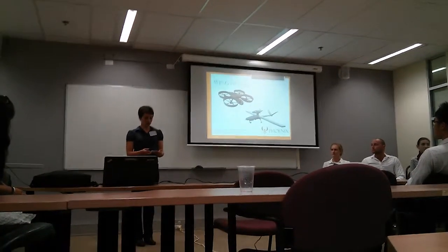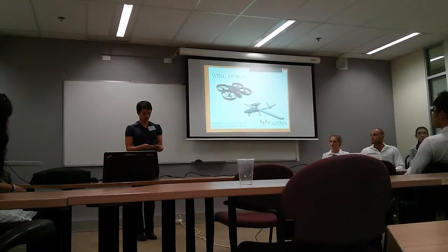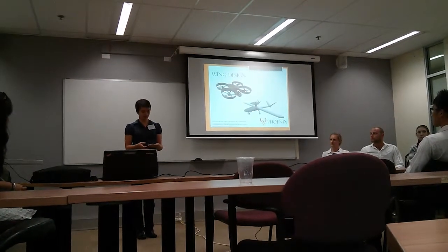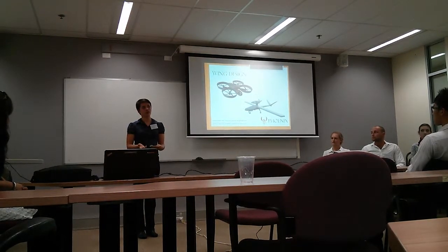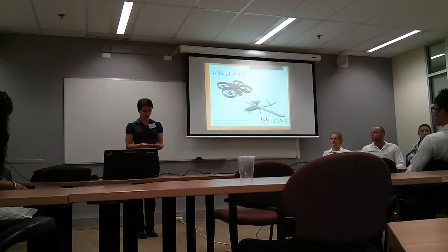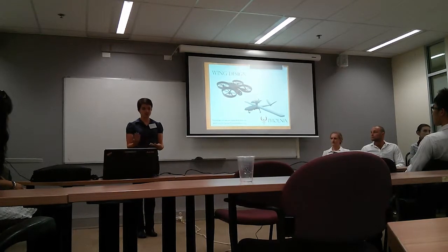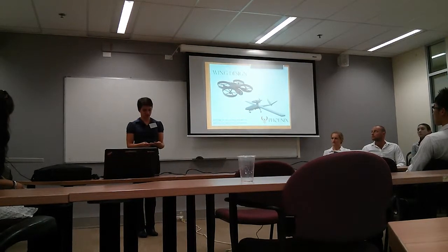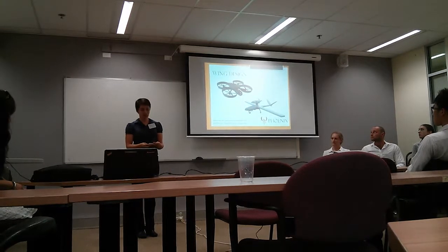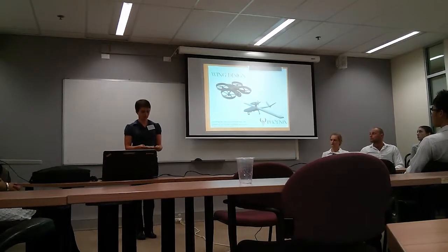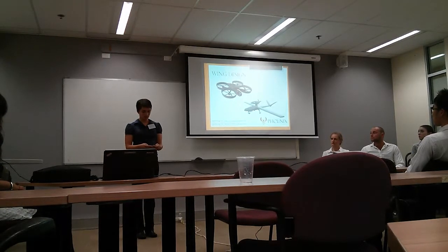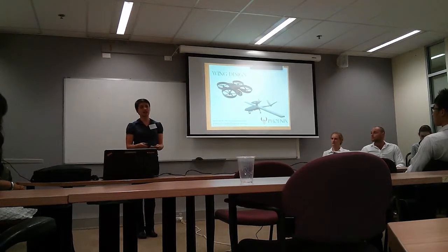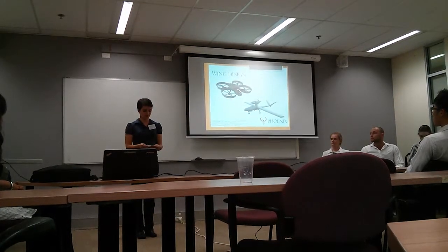Due to the way in which the wings are designed, lift is produced by forward movement and rudders are used for steering. A rotary wing UAV, on the other hand, produces lift by using rotor blades that rotate around the mast, and steering is facilitated by changing the relative speed of these rotors. The most typical type of rotary wing UAV is a helicopter, but UAVs tend to use 4 rotors, and these are known as quad rotor UAVs.